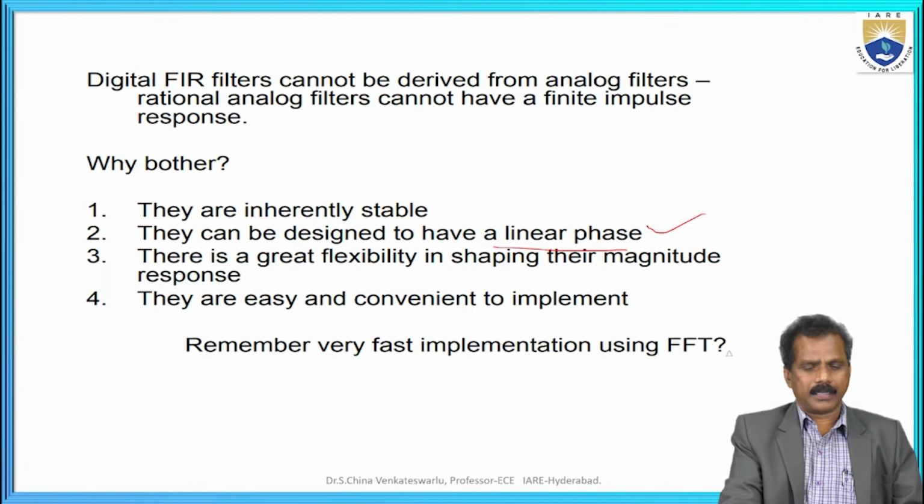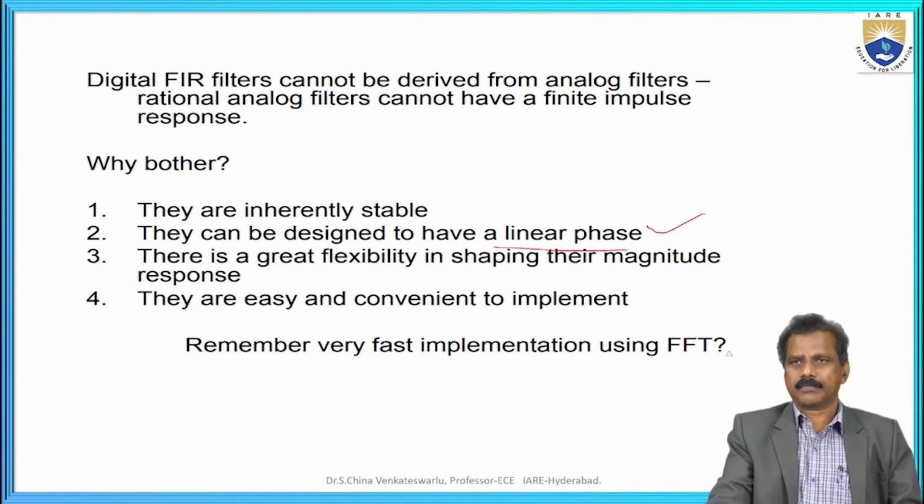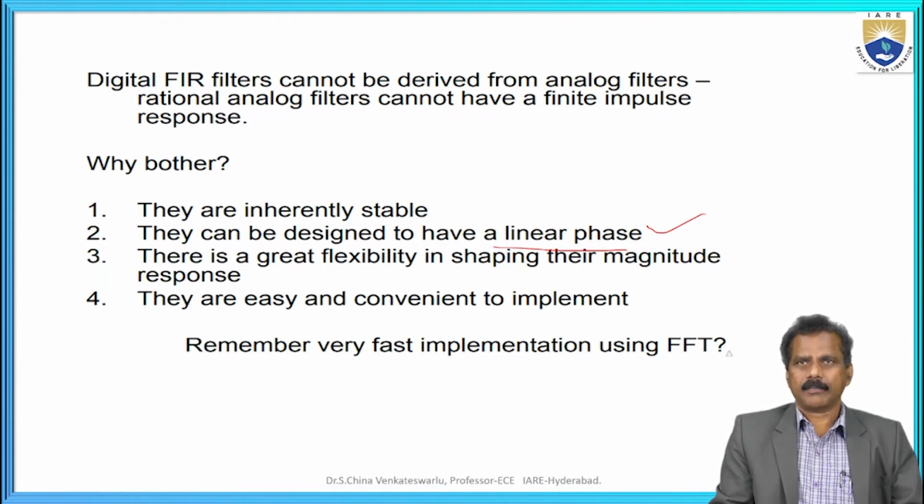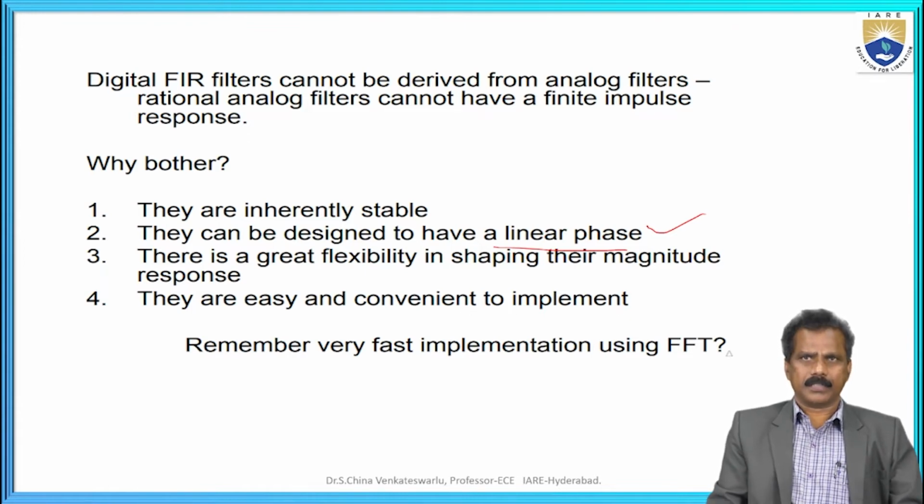They are easy and convenient to implement, including very fast implementation using the fast Fourier transform. So digital FIR filters cannot be derived from analog filters, meaning a rational analog filter cannot have a finite impulse response.